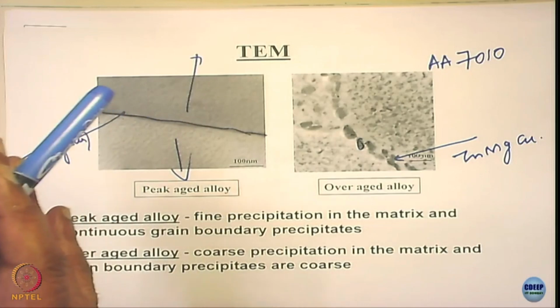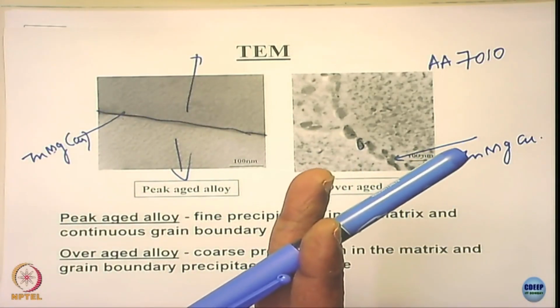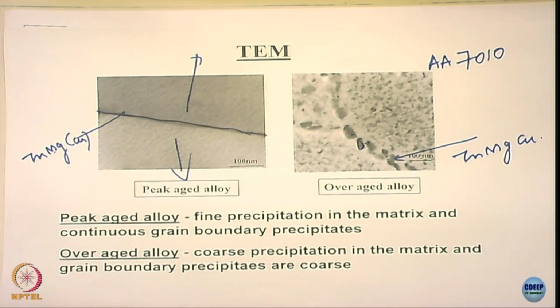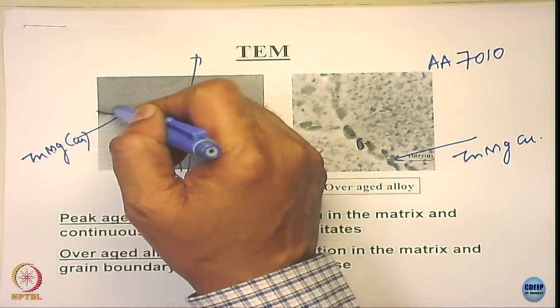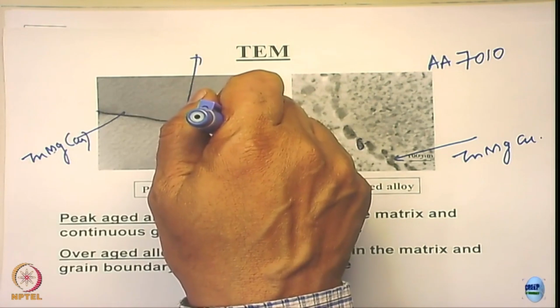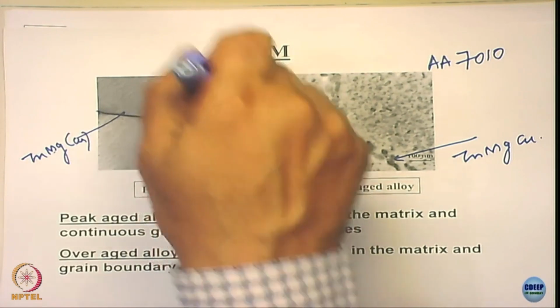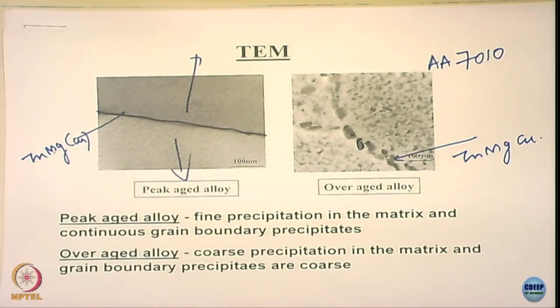So there, basically the matrix passivation does not get affected, but what is happening instead? The precipitates which form on the grain boundary are selectively attacked because they are relatively active compared to the aluminum. So the mechanism in stainless steel is that the chromium, which is passivating, is getting depleted, and so grain boundaries are getting attacked.